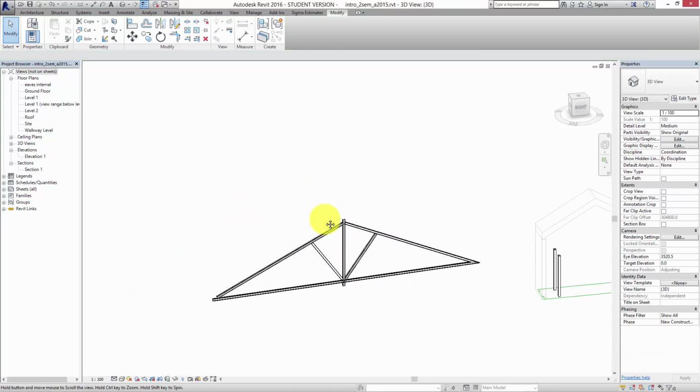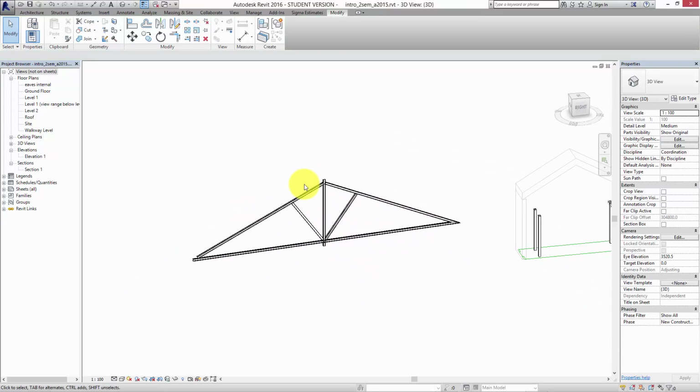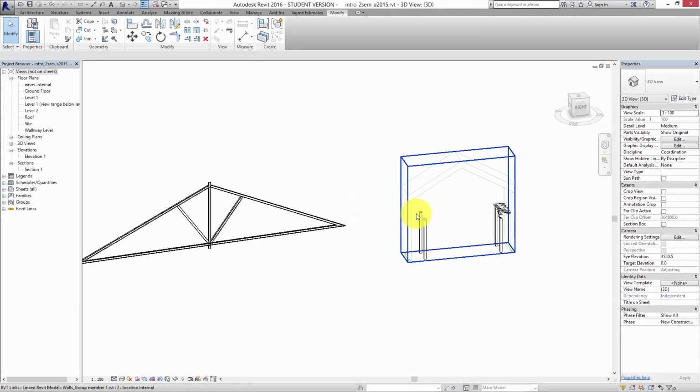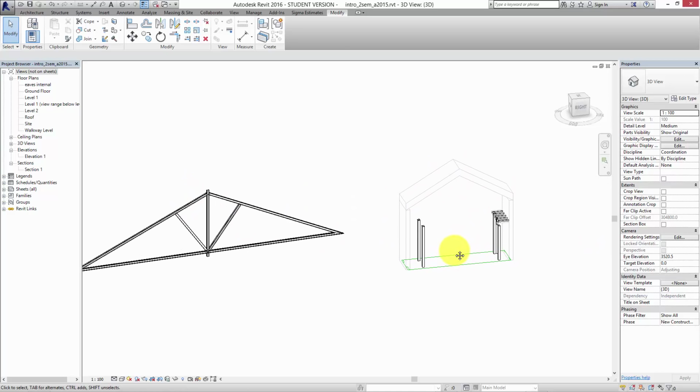I haven't done this to any particular level, but you have set up your levels within your cross section here. So when you're drawing your truss in place, you'll have a level for what the ridge is at. So all you need to do is go to that level in plan and draw a beam on that level. And that's it. Okay.